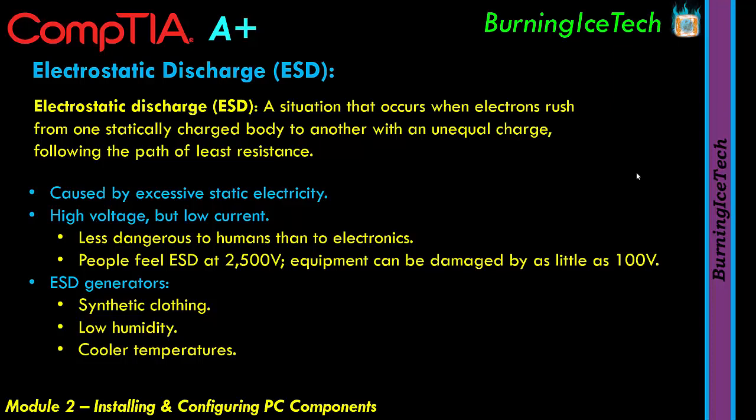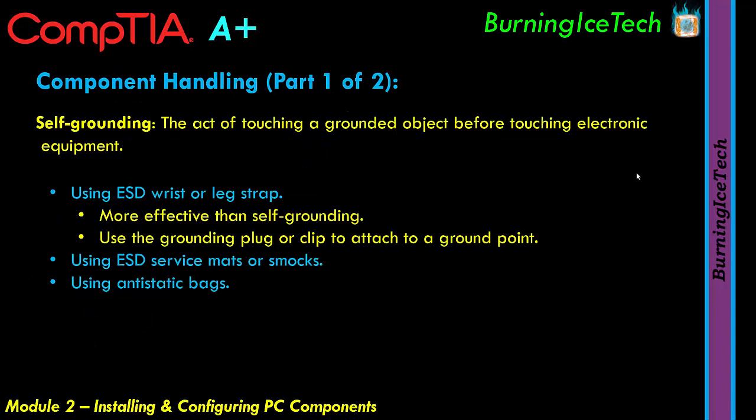So that's just going to help you guys. Alright, so as you can see, the next topic is component handling, and ironically now they mention self-grounding, which is pretty much what I just explained to you guys. When you go and touch that metal case, you're releasing that static electricity into the case itself safely.